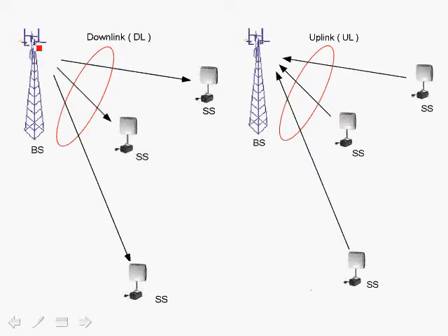The base station is in transmit mode and sends a packet consisting of multiple OFDM symbols and a preamble, of course prior to the symbols, that all subscriber stations use in order to do channel equalization, acquisition, carrier offset estimation, correction, etc. We'll talk about the acquisition later.